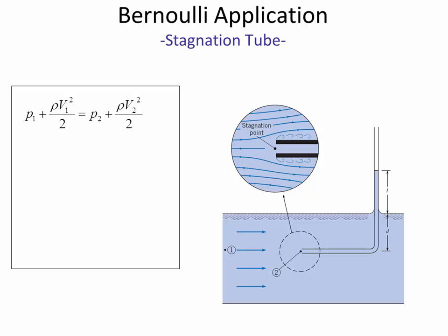If you had an angled tube or a straw and you put it down into the flow, then there's going to be a point at which a streamline stops, because inside of the straw the water level is going to rise above the normal liquid surface to an elevation that is related to the pressure at the opening of the tube. The pressure at the opening of the tube is partly related to the depth, but the water wouldn't rise if this was just stagnant water. The water inside the tube would be at the same elevation as the surrounding water surface.